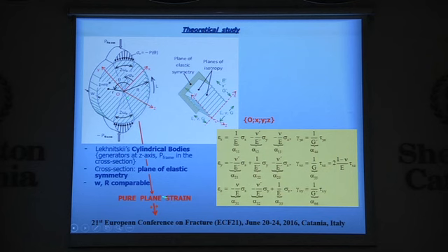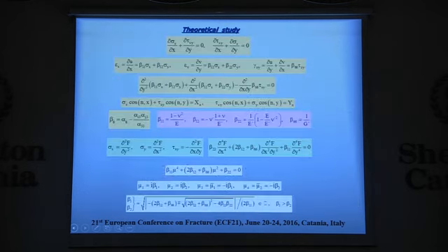We have a pure plane strain, and in that case, the equations characterizing the elastic equilibrium of the body boil down to this set of expressions: the equilibrium equations, generalized Hooke's law, the one compatibility equation, the analog of Beltrami-Mitchell in terms of stresses only, and the boundary conditions, all given in terms of these engineering constants.